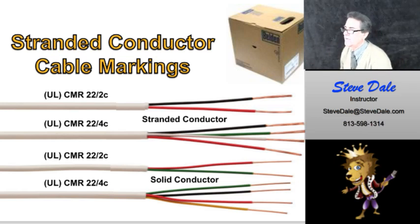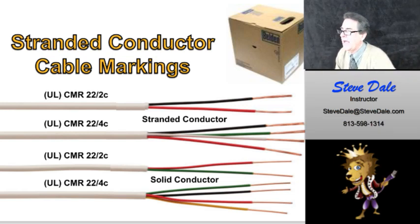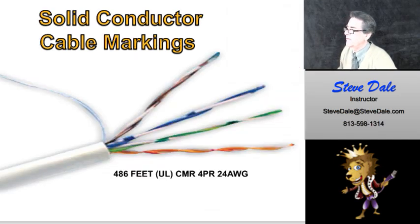So there's a difference between twisting the insulated conductors, which would be like category cable. So what you need to know here is, what does 22/2C mean? What is 22? The AWG number, the size. This is what's marked on all cables. 22 is the AWG number. 2 is the number of conductors. I'll explain CMR later in this presentation.